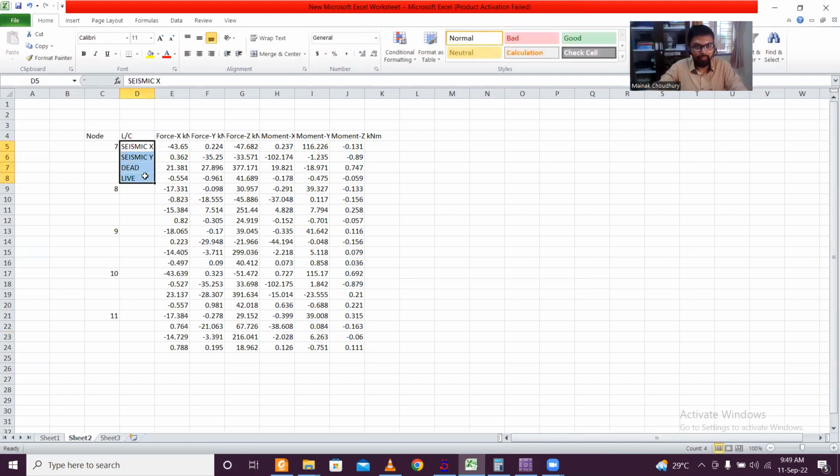Then you can just select this, copy, and then paste. And here also, just the coordinates, you can just copy this again and again. And then you have another option for the column sizes, and the column size is 300 by 300 in our STAAD.Pro.